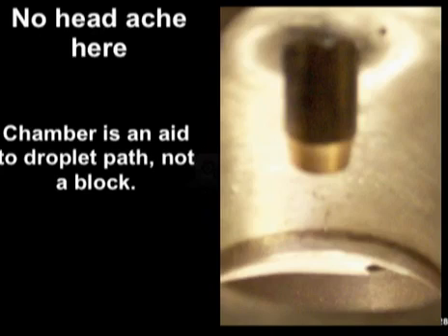The other thing that we're working on in the short term, when we're using directional ports, is we're actually beginning to make them more abrupt and sharper. What we had learned from some of the import directional ports is they leave them completely sharp. A lot of times when we're using the valve as a directional aid, it's not directly in the flow path, but it becomes part of what supports the flow for the in-cylinder action. You want the flow to break away from the short turn rather than try to follow it, so that you can keep the charge together. So we've actually begun to make that fairly abrupt.